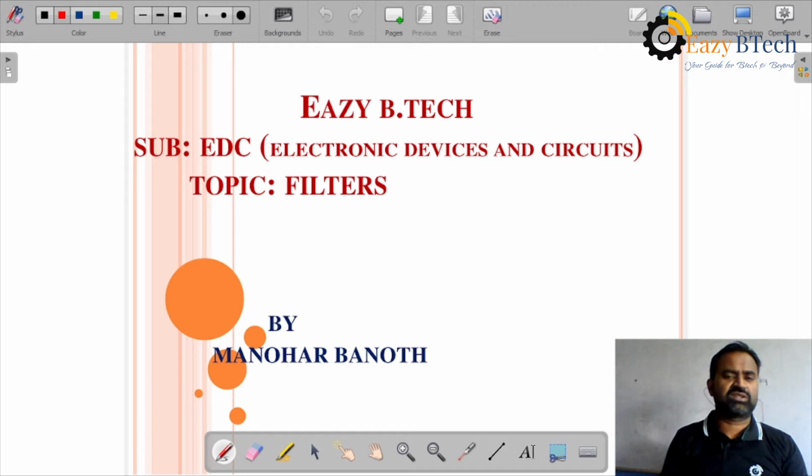In the previous lectures, we have studied the first stage is a transformer, which converts 230 V AC to 9 volts, 12 volts or 5 volts of AC. This voltage rating can be done using a mutual induced transformer. Then we have a rectifier, which converts AC to pulsating DC. Then we have filters. For smoothing purposes we use filters. Filters are used to remove the unwanted AC portion. The unwanted AC portions are ripples present in the output of the rectifier.